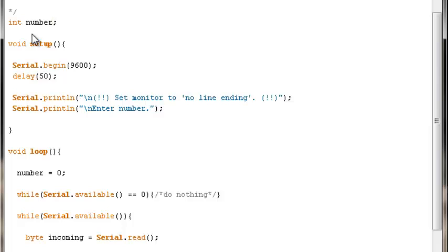instead of leaving it hanging. At this point the Arduino has set aside a block of memory that corresponds to the size allotted to the integer type variable, and there's a name attached to that block of memory, but the value could be anything left in those registers. We don't know what that value is. So in order to know what it is, all we have to do is assign it the value of 0. Now we know. And that's just good practice.